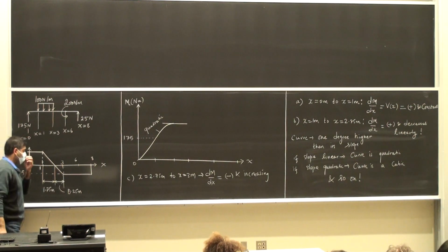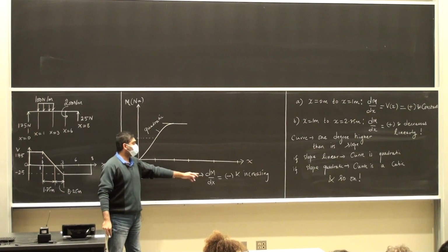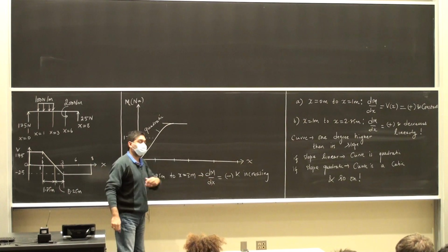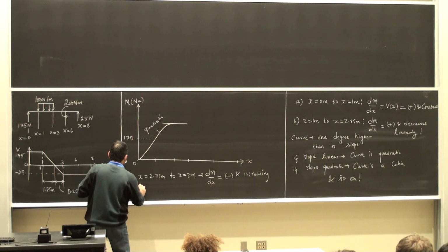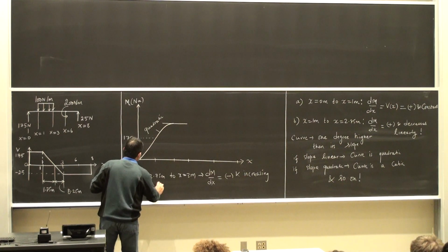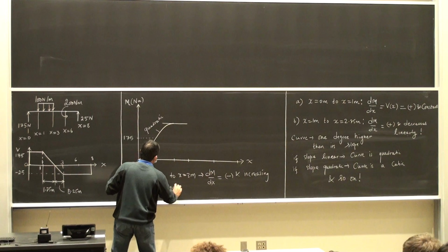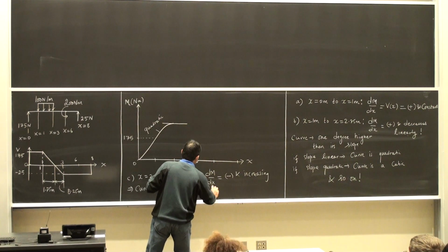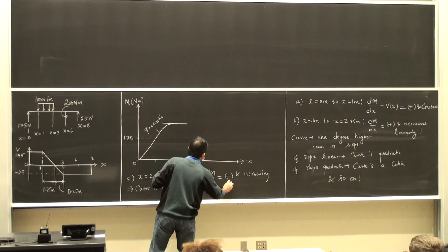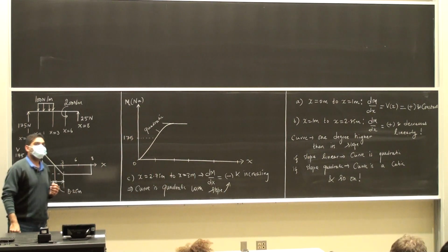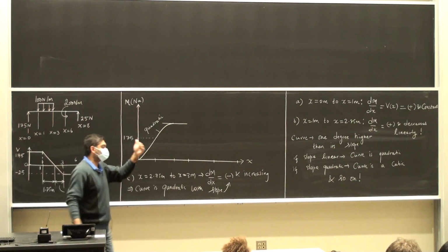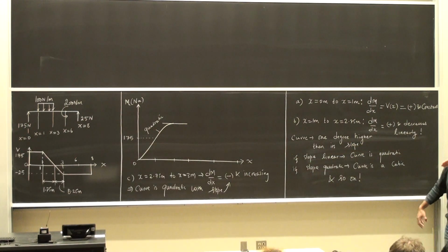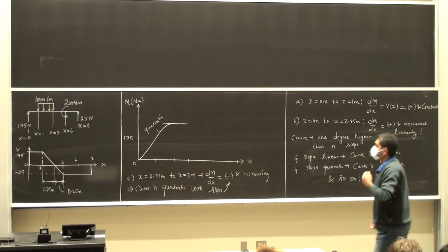Which tells me that the bending moment curve is going to have a quadratic shape with slope given by that. The slope is negative and increasing. So I am falling down essentially.